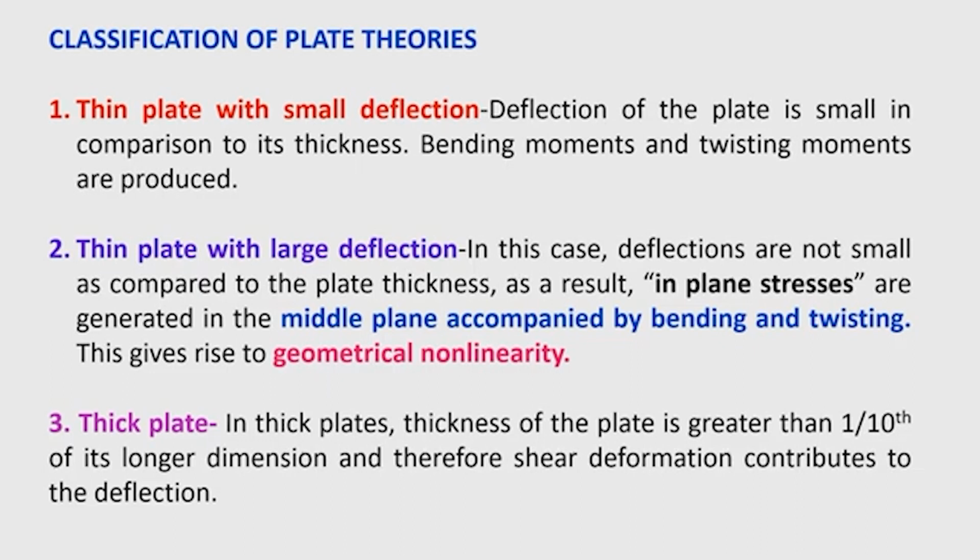So, thick plate theory considers the shear deformation in the deflection of the plate, whereas in the thin plate with small deflection, the shear deformation may be neglected, is insignificant. Similarly, in the thin plate with large deflection, we need to consider the geometric nonlinearity in the governing differential equation of equilibrium.